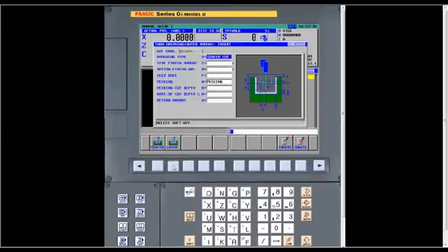If you want to use layering, it only takes layers out. It'll go down so far, rough it completely out, go down a little further, and rough it completely out. That's how that works. But if we use center cutting, then you can leave, again, you can see both of these next two fields have asterisks where you don't have to answer that information. You can, but you can leave a certain amount of finished stock.